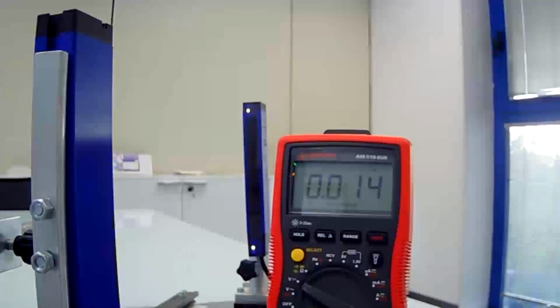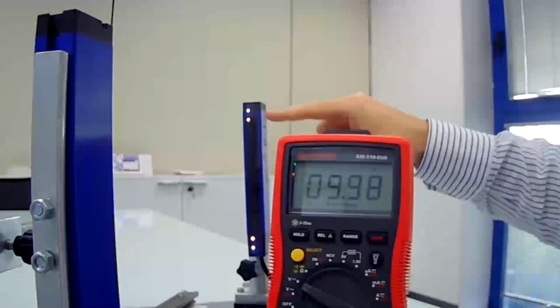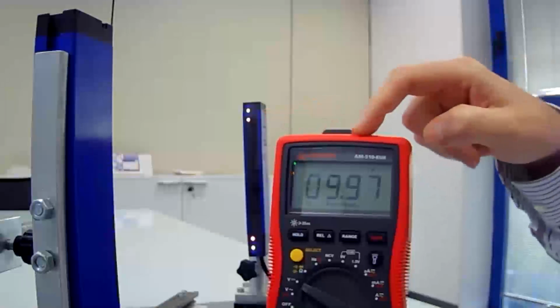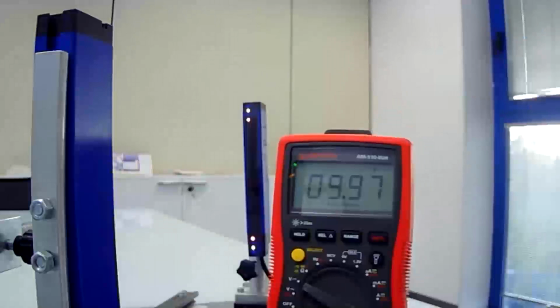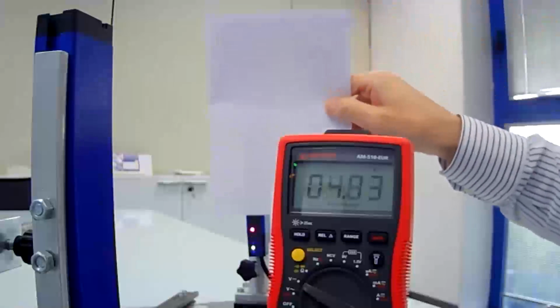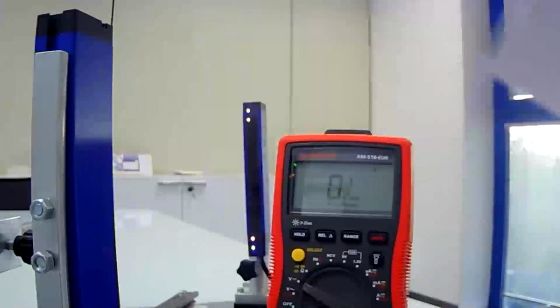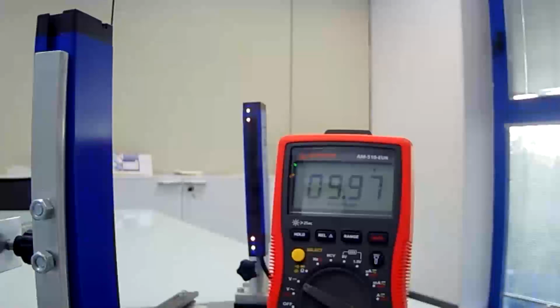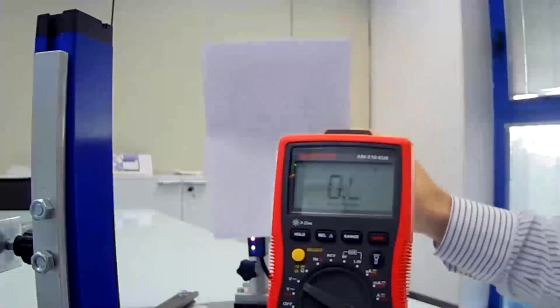So the procedure is the same: connecting the selection wire to positive and restarting the model. After a while, we can see that the digital output is now activated, but also that the analog output is working in a reverse mode. So now we are working from 10 to 0 volt, while in the normally open or positive ramp, we work from 0 to 10 volt.